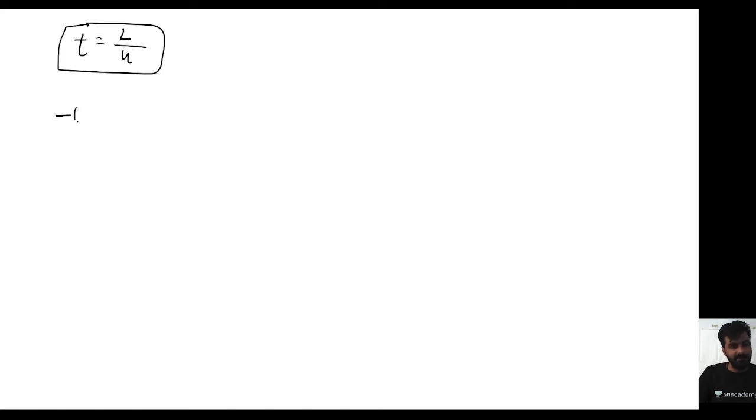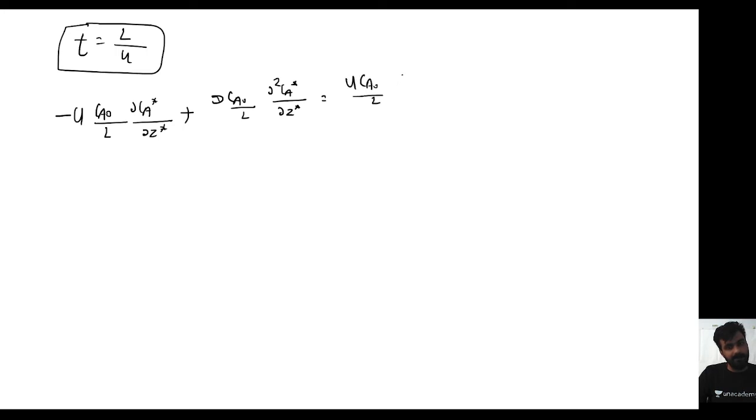So can I write the equation: minus U Ca naught upon L del Ca star upon del z star plus D Ca naught upon L squared del 2 Ca star upon del z star squared, equal to U Ca naught upon L del Ca star upon del t star. I have only put all these things over here.